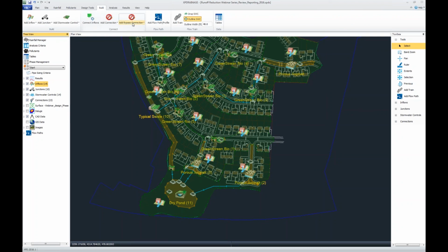Well, you're not going to have a rain garden treat that. You're going to have a high flow bypass system. You can represent that by a bypass channel or maybe another vault with control structure and underground pipe. So we're going to be able to assess both of those systems.